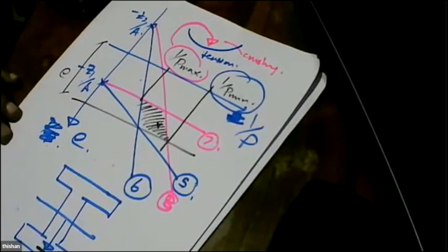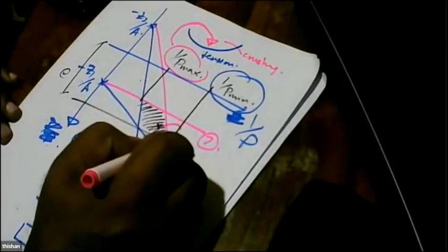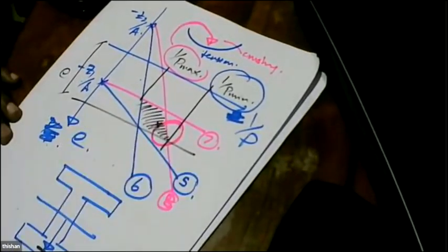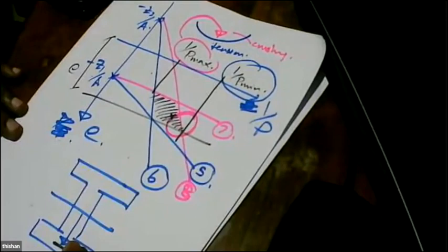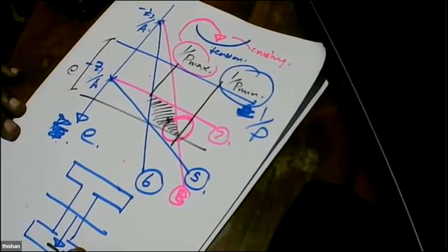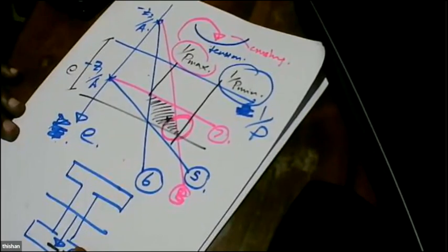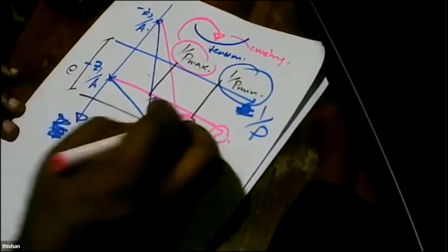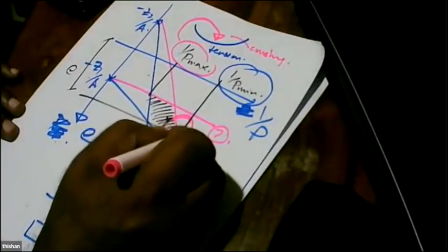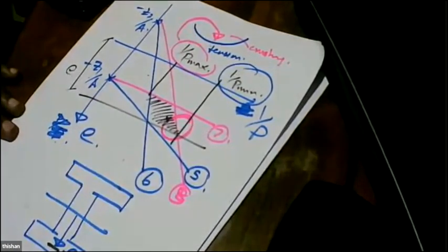Right? So because of that reason, when you are selecting, we always like to select as close as possible to the minimum. Why? We know these pre-stressing tendons are expensive. So if you want to have an economical solution, we must always go for the minimum value given here.